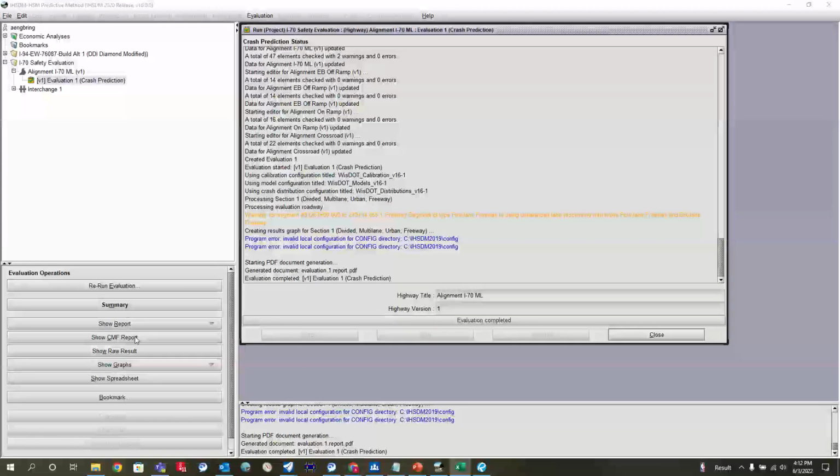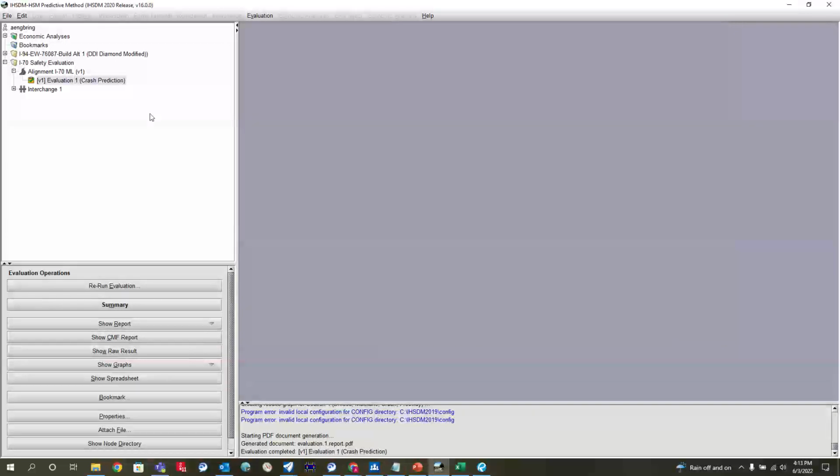Eric will sometimes have you look through those, or he'll check through those to find if there's anything egregious sticking out that is really skewing the results. Things that we've seen have been really small horizontal curve radiuses, like less than 100 feet, will really skew the results, but they're easy to identify from that sheet. So that's the last section that I had today.